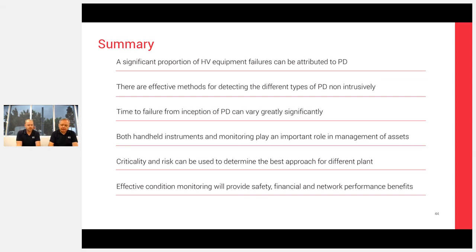I don't think it really happens as often as all that anymore. If you're testing offline, you're taking switchgear out of service, and you're potentially not testing the cable termination because of the capacitance of the cable. So you wouldn't be able to test cable termination and the VT, and they're two critical areas. But we're talking online in terms of our periods.